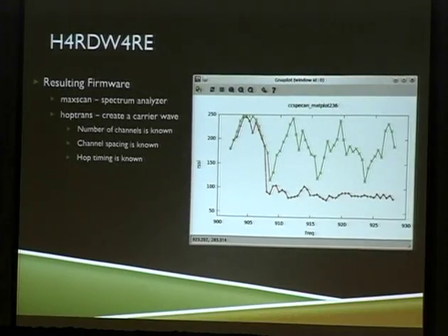So what happened at the end, 2 days ago, is that I got 3 basic programs. We started off with the spectrum analyzer, and you can see the output right here. The green line is the max values that we're receiving, and the red line is what we were receiving at that second or millisecond. Basically, this is data that is being scraped off by the GoodFET and just pumped out using Python's GNU plot. It's not as quick as the display provided by the IME, but as you can see, we can see certain patterns developing, and that's what the second one was, the hop trans.